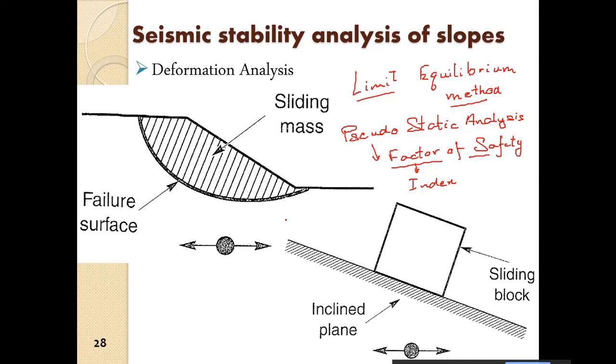Especially after an earthquake, as we have seen, there may be a significant amount of displacement induced in the slope, and therefore to assess the serviceability of the dam, we have to be able to assess the total deformation after an earthquake affects the particular dam. For that, we have developed various deformation analyses.